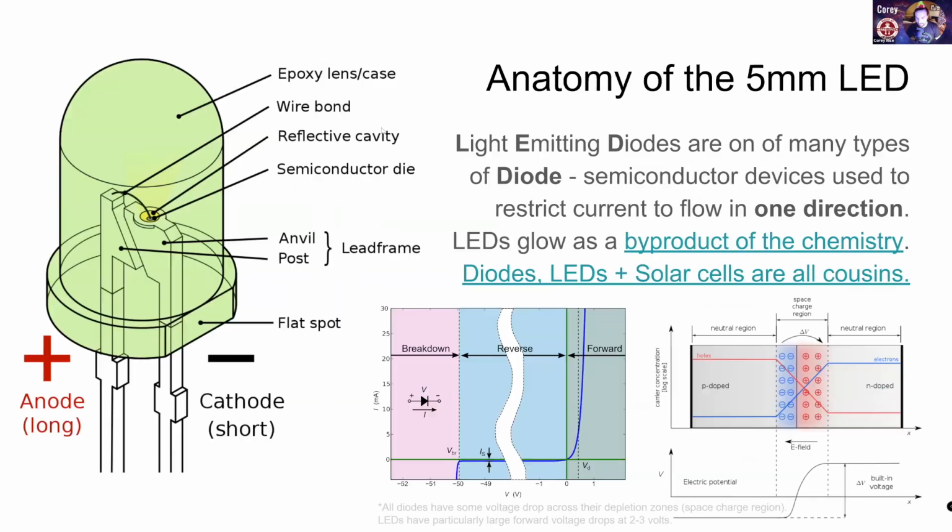But let's see, if we're headed back to here, this is a link to a video where you can see a little bit more about how those are related. And what's useful here is to take a look at this particular graph, and we're not going to decode what all of it means. But there's this point where if you have enough voltage applied to an LED, all of a sudden the current will start to pass through it, but only in one direction. If you have a voltage build up in the other direction, up to some point where it'll break, it will stop the current from going backwards. And so that's the point of a diode. An LED is just one of those that glows when current goes in the right direction.